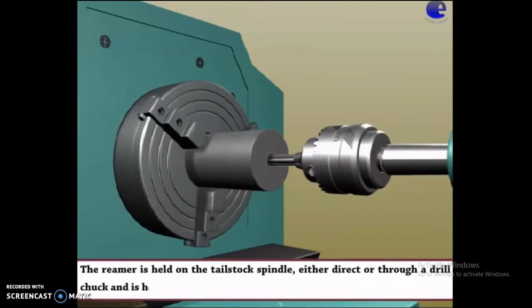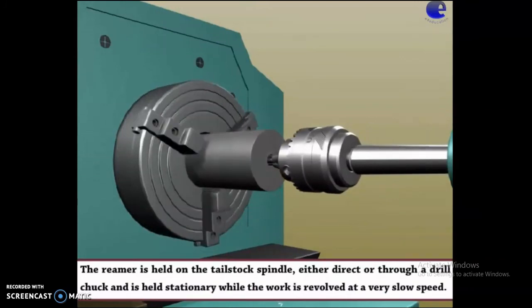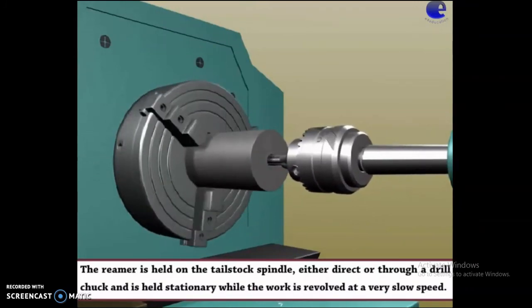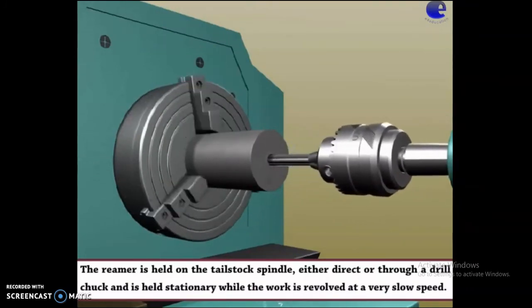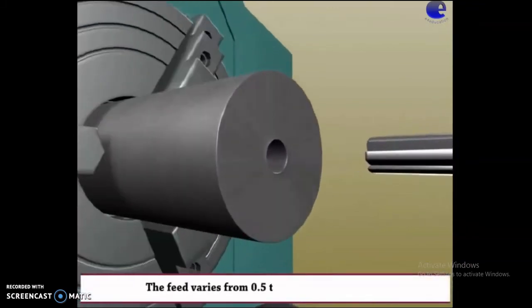The reamer is held in the tailstock spindle either directly or through a drill chuck and is held stationary while the work is revolved at very low speed. The feed varies from 0.5 to 2 mm per revolution. Hence, reaming is done.